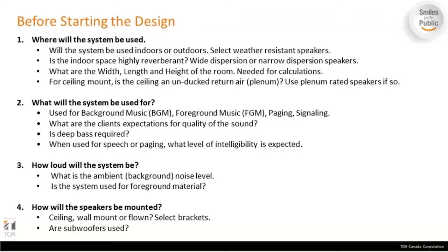And moreover, not all spaces that you will be designing will be acoustically treated. There are always going to be acoustic anomalies, right? Not every space that we go to design will have a carpet flooring or will have acoustic panels, right? Like we see in installations for mosques and churches where they use highly reflective surfaces, which poses as a challenge. So you have to note all of that before you proceed with the design.